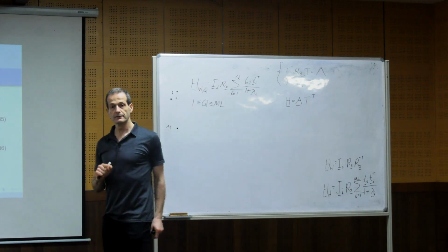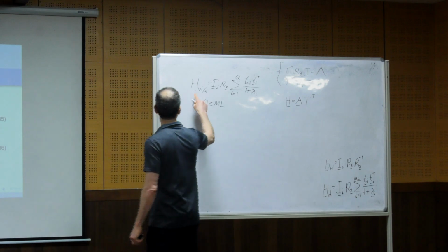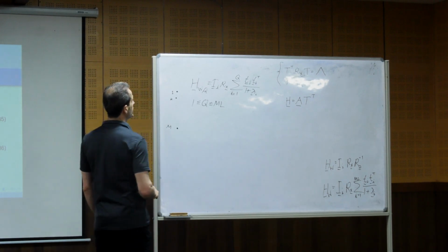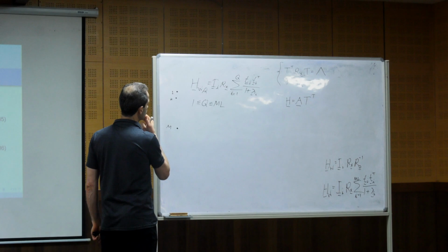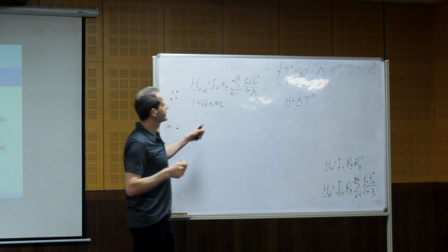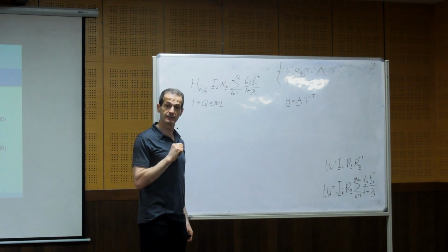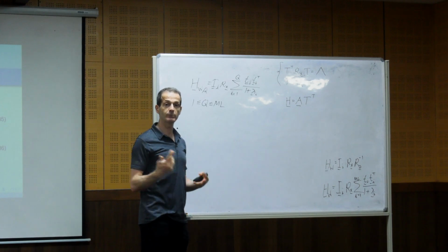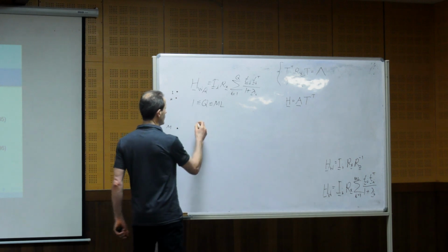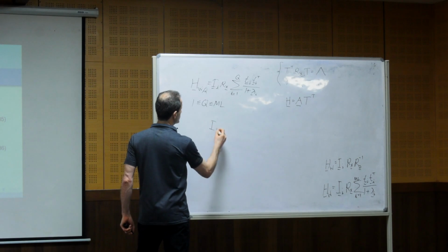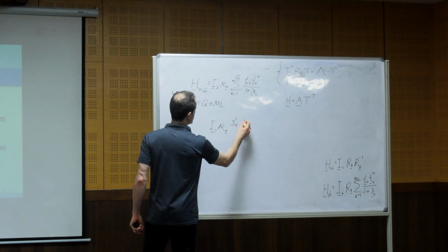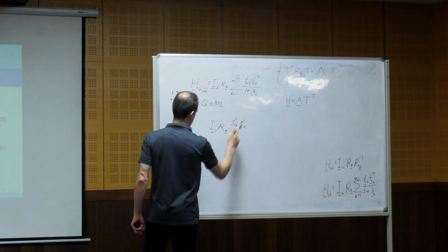Any questions so far? Okay, so we talked about the variable span Wiener filtering matrix. We also showed some examples, and we saw that if we take the first element, it generates a way to maximize the output SNR. So if we take only the first element, which looks like that, T1, okay?